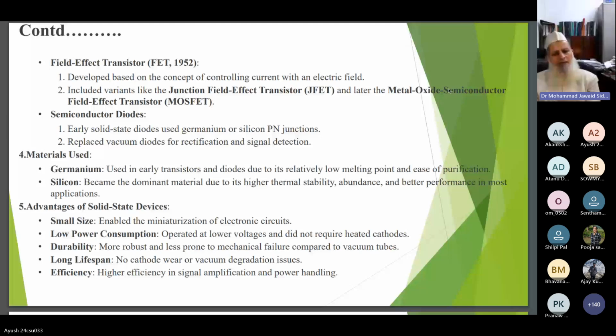Static power in the case of CMOS is almost zero. Dynamic power is there. Dynamic power means that when the state is changing, either from 1 to 0 or from 0 to 1, then only current flows and some dissipation occurs. So that is why the field effect transistor MOSFET became very popular.